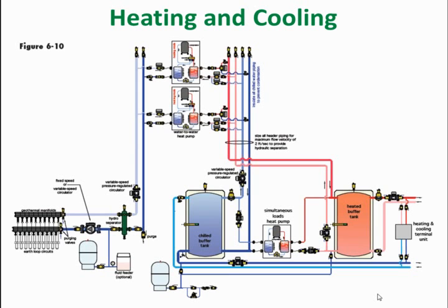All right, heating and cooling, what else on this? I think that's pretty much the same thing. One thing that we're trying to bring to the geo industry is the concept of expansion and air elimination devices. I know a lot of the geo guys that are plumbing out there now don't bother putting in the air elimination devices, either a central air elimination device, or you can see a little air elimination on the hydro separators that we've shown in these different drawings, and expansion tanks.